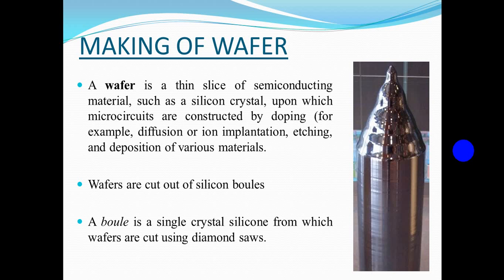Once the seed crystal touches the surface of the silicon, the melt temperature is reduced. The silicon melt attaches itself to the seed crystal. Once the crystal starts to grow, the seed crystal is raised out of the silicon. The seed is rotated in one direction while the crucible in its holder is rotated in the opposite direction, and the single seed crystal becomes a huge ingot. This process is the Czochralski method of crystal growth.